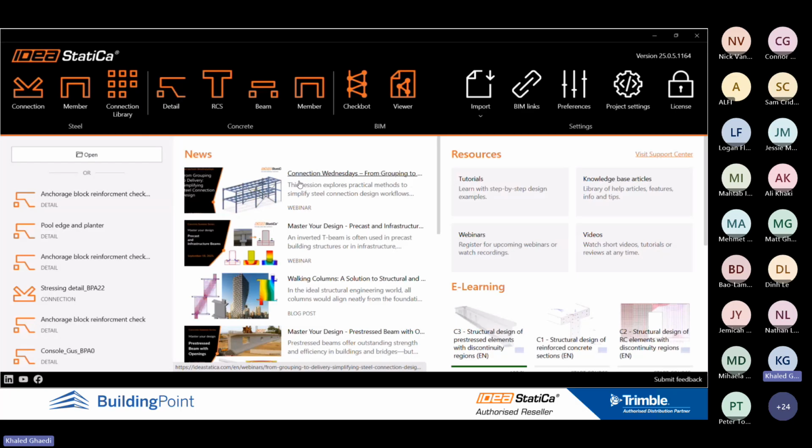By the way, here you can just customize your report as you wish. Once you have selected what kind of report you want to include, you can go to regenerate, and here you have the detailed report, including the reinforcement information and all the results that we reviewed, the stresses, strain, the direction of the stresses as well. So you have all this information, let's say graphically, and also in tabulated format for strength and also for serviceability. And also you can get the bar bending schedule for the reinforcement as well. And also you can include the explanation and theoretical background of the method in your report as well. So this is about the detailed 2D. So hopefully it's clear.